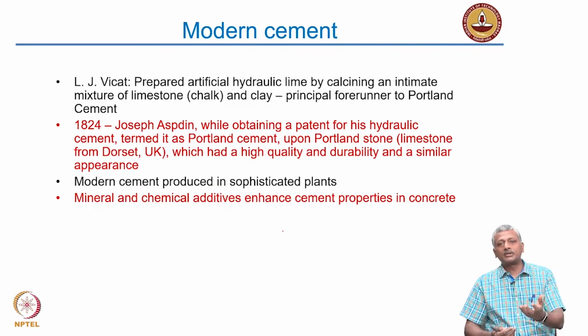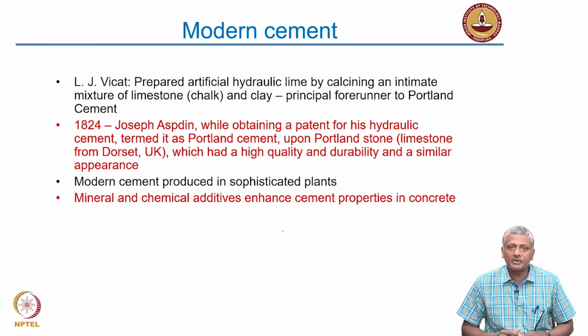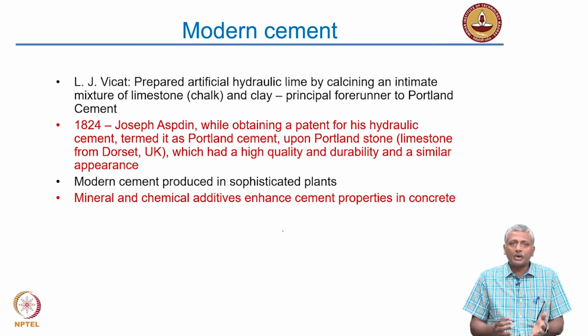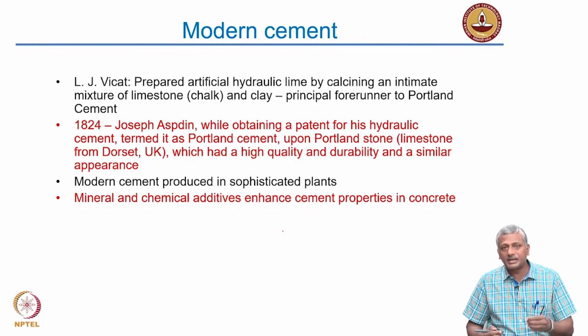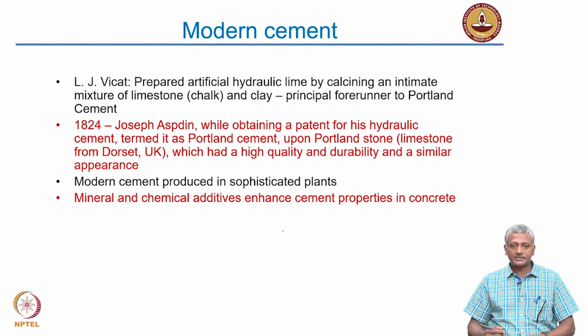So to produce lime, what they do, they just simply burn limestone. Then people started realizing, okay, now if the limestone is not very pure and I burn it, it seems to be giving some very interesting properties in the mortar. What if now we take limestone and clay, add the impurity first and then burn it together? And that ended up producing cement-like substances.